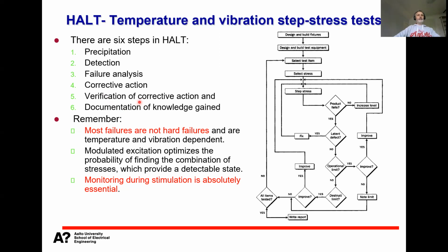But we need to remember that most of the failures, or at least a large fraction of them, are not hard failures. A hard failure means that something is permanently destroyed. Because of the combined temperature and vibration loading, we may have temporary failures, so-called soft failures, where something is temporarily out of order. Like the previous example of an electromechanical connector: the contact interface is not in proper contact just during ramp up or ramp down, so the local resistance is high.